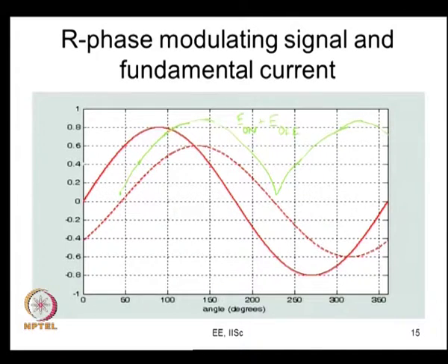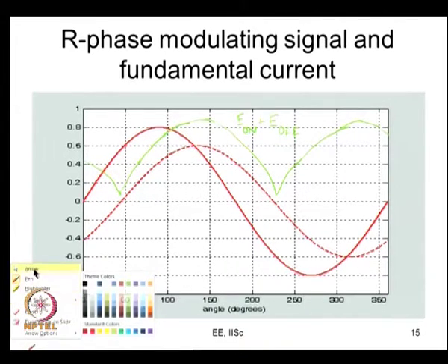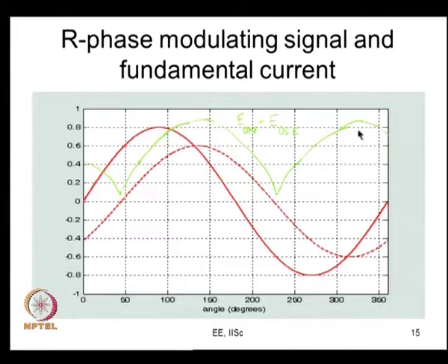So, this is how the nature of variation of E on and E off is going to be. How is this variation? You can say it could be roughly sinusoidal if you ignore certain things, if you say that this is proportional to the current. So, you can evaluate a certain average value. You would take it as the average switching energy loss and multiply it with the switching frequency to calculate your switching loss, the power that is lost here.